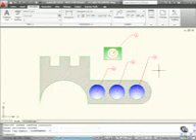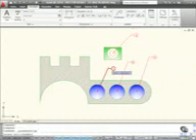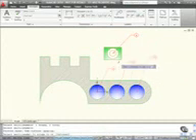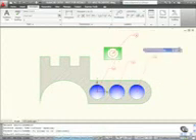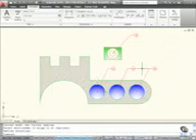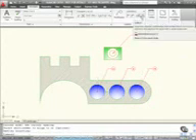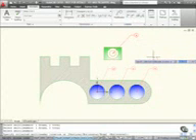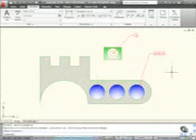So there's my bubbles there, but look, I can align them. If I align them all, so if I select 1, 2, 3, and right click, multi-leader here to align to. Let's align to number 2 there. Align them all across, and they're all aligned with number 2. I can also collect them. So I select here and select my multi-leaders. 1, 2, 3. Right click to confirm, and look, they are collected multi-leaders. All the bubbles on the one multi-leader line, like so.